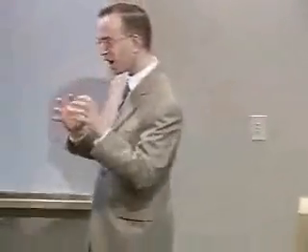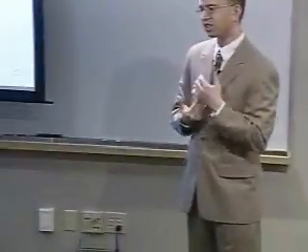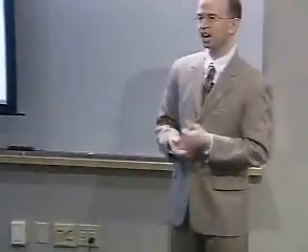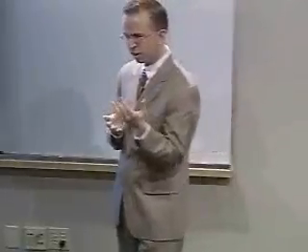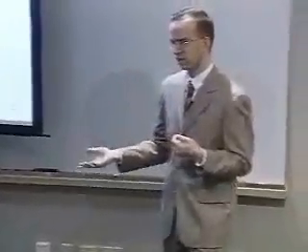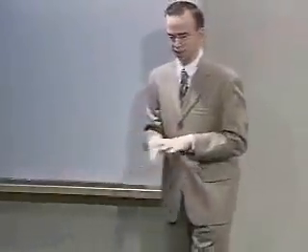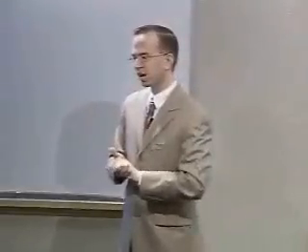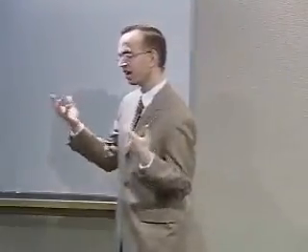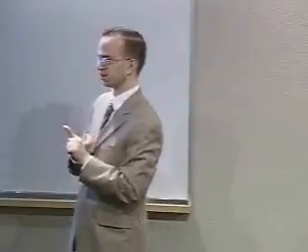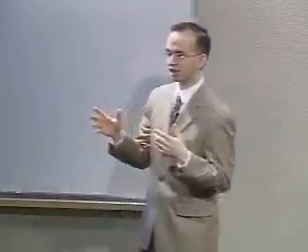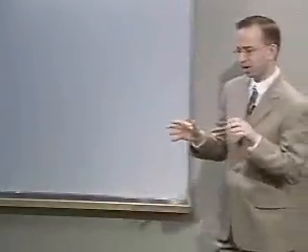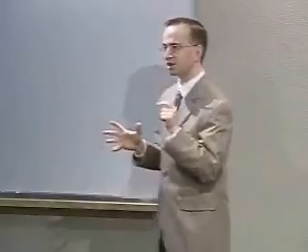All right, so with the power of emulating signal propagation comes the challenge of doing it in a good manner. I emphasize again that the device behavior is real, so I don't make any assumptions about interference range, reception range that you typically read in a simulation-based paper. All of that is real. The device just does what it does. So there are three different approaches that we have used, or three different categories of approaches that can be used. We've used two of these so far in emulating signal propagation. The first is modeling. And this is typically broken into two parts, large-scale path loss and small-scale fading.